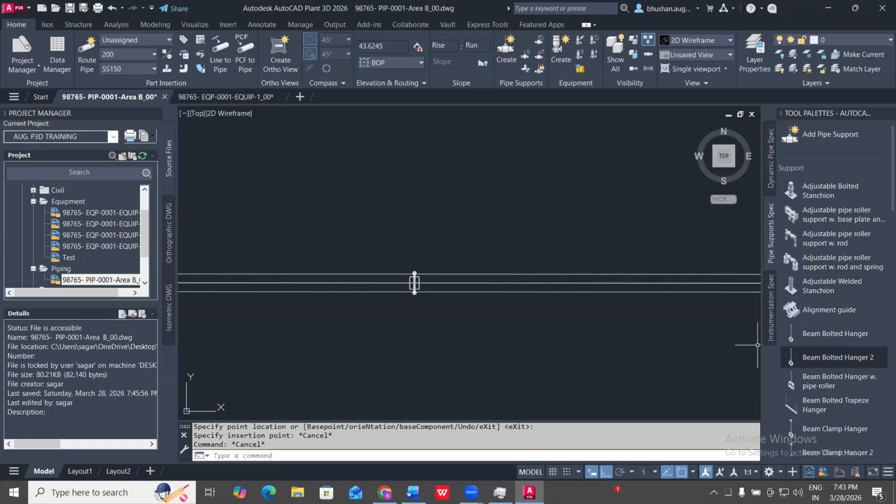Then we learned about the compass, that very helpful circular tool that snaps your pipe to standard angles. Then we understood the different elbows and bends and how to create pipe bends. We then explored the continuation grip, both for extending a pipe and for creating branches. Then we learned a powerful substitution grip for replacing fittings without rerouting.